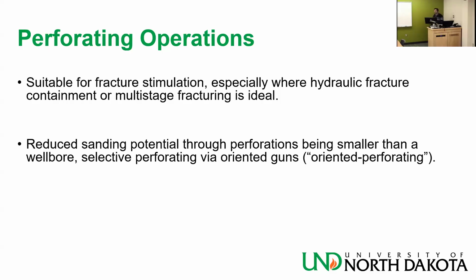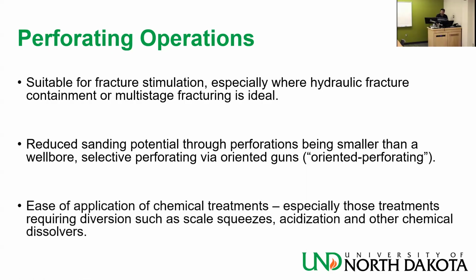There are also techniques involving oriented perforating, where we orient perforations intentionally in a certain direction in order to achieve something favorable during the hydraulic fracture treatment. Perforations also ease the application of chemical treatments, especially those requiring diversion, such as scale squeezes, acidization, and other chemical dissolvers. Those go through the perforations, so they always help.